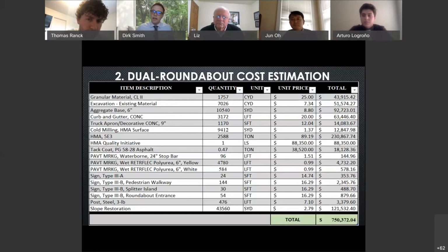There's not a lot of seen pedestrian traffic. They took note of it in their traffic studies, and it was noted that there wasn't a lot of pedestrian traffic. So it's something that we didn't consider specifically for this project. However, we did consider in our schematic roundabout design and estimate signage and striping for pedestrians to cross the roundabout safely.